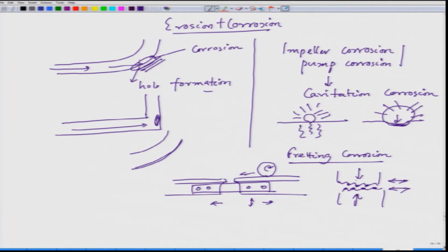So, a kind of erosion is taking place, or wear is taking place. And now, once the train goes out, they might get oxidized because the temperature also goes up. So, now you can have oxidation first and then erosion, or erosion first and then oxidation, and finally, you would see that in these small dips, there could be a possibility of debris accumulation. Those debris will act further during the next fretting action when the train moves. So, this is the typical fretting corrosion.